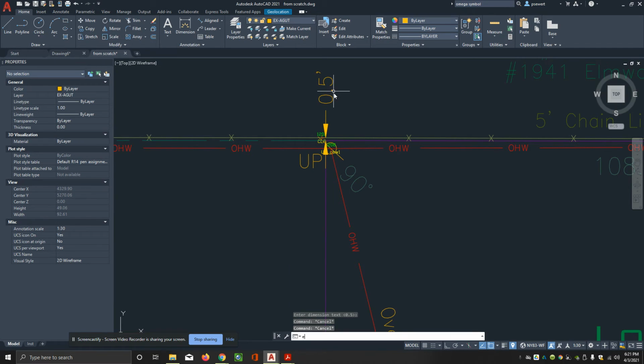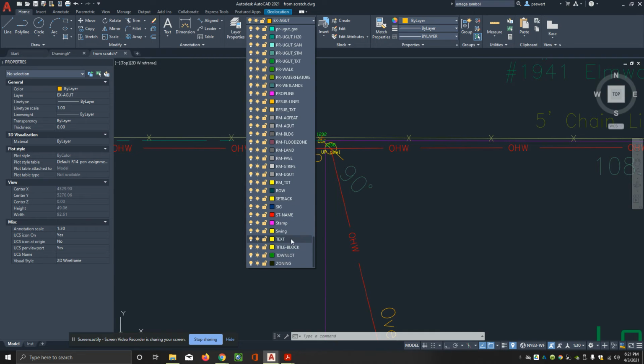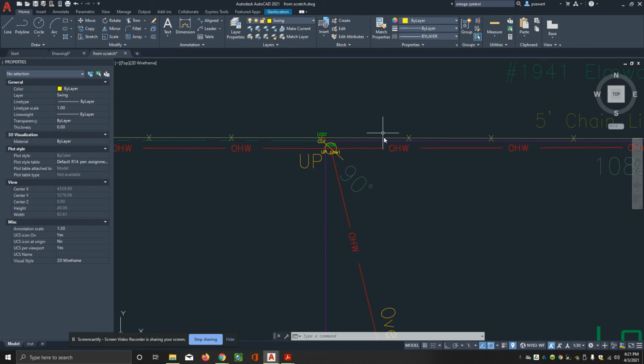Are you locating there the fence off the property line? Yeah, we're defining exactly how far this chain link fence is away from our boundary. It's somebody else's fence, probably not ours. Oh. So we're seeing how far it is away. Legally wise, they want to see the answer below 1 foot. So anything below like 0.9 is a good answer to them.